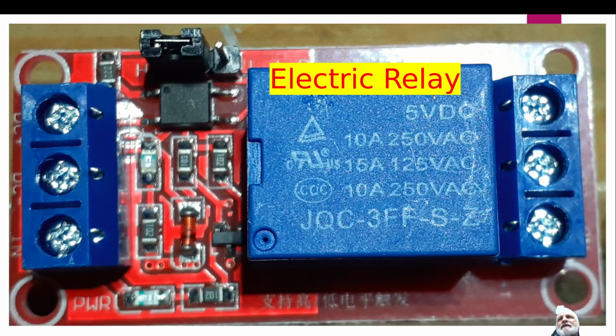Okay. This is an electric relay here, and you can see it says 5 volts. And so you can activate this with our 3.3 volts, up to 5 volts, from our Beaglebone, and we can activate this relay. And then on the other terminals, you can actually power something very large. So you see this says 250 volts AC at 10 amps.